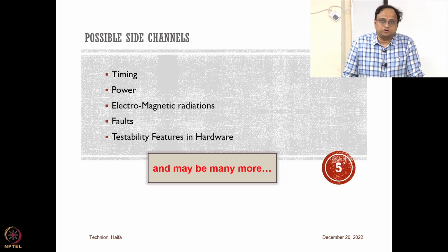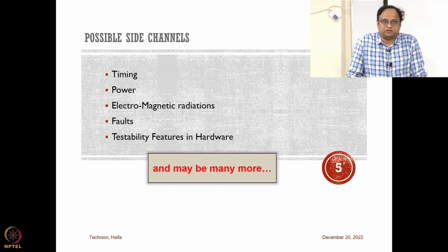When you go home, you can do a Google search on a very famous attack which was recently published, called Plundervolt. Plundervolt is an attack that targeted Intel's SGX machines and showed how somebody tweaking the voltage frequency scaling of these computing systems can create faults and faulty ciphertexts, and from there get the key.